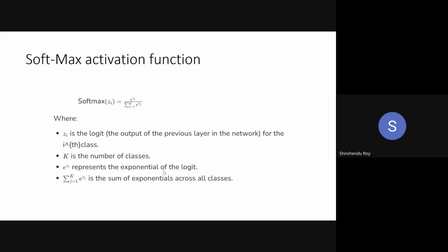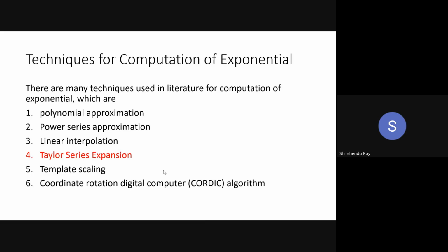So now I will move on to the exponential function only, because these applications were already discussed in other sessions. I will not repeat this. So moving to the exponential function: there are many techniques or algorithms used in literature for computation of the exponential function, like polynomial approximation, power series approximation, linear interpolation, Taylor series expansion, temporal scaling, or the CORDIC algorithm. Authors have used these kinds of algorithms to compute the exponential efficiently.